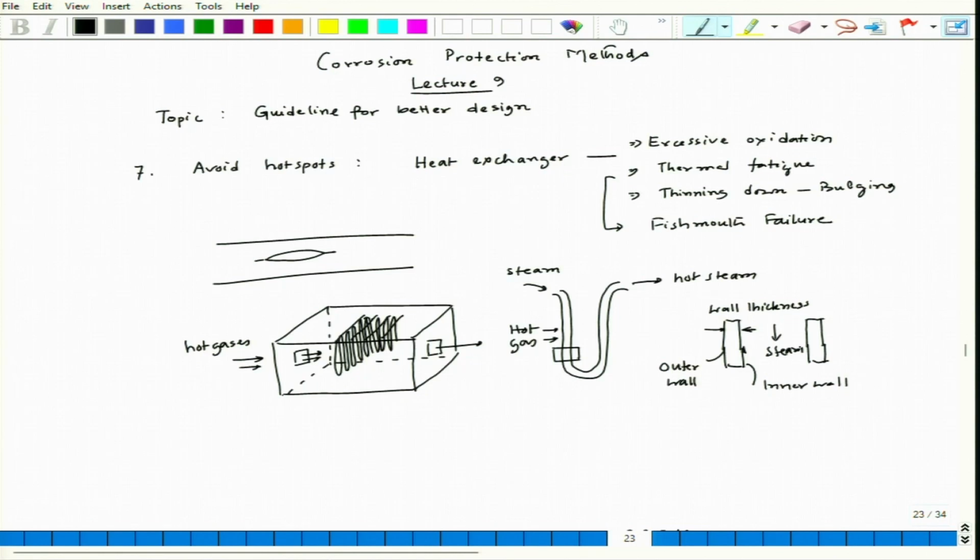And by chance that steam is getting obstructed because of some eventualities there. That obstruction can lead to turbulence in the flowing steam, and also there could be a pressure drop. From this point to this point there could be a pressure drop, because at this point we have sufficient pressure and this point is obstructing the steam flow. So, there will definitely be a pressure drop.